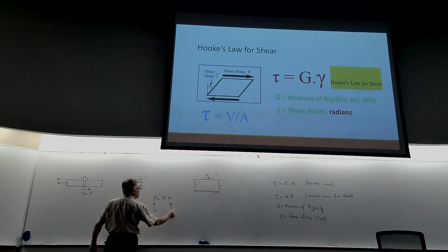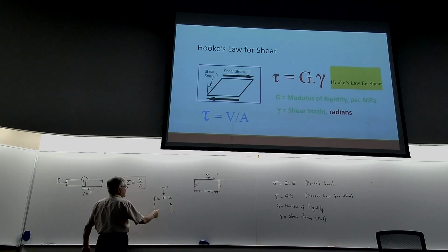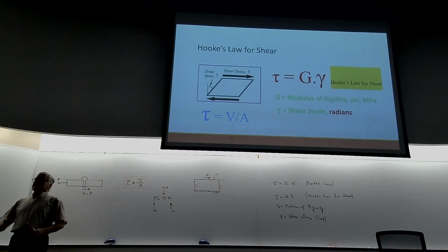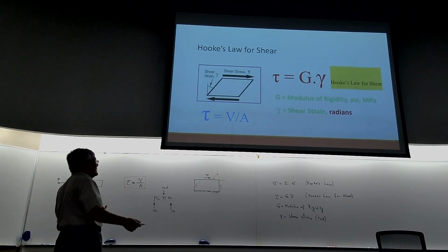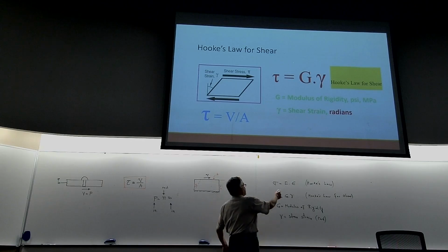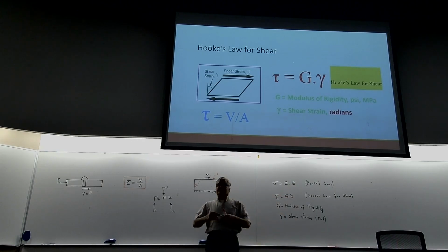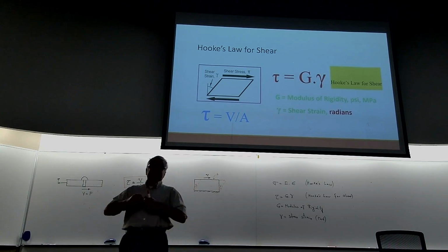Diameter also in inches, and pi is radians. So if you cancel the inches, you find that a radian is just there by itself. So it is not a real unit. It's a reminder that we are not doing degrees. So radians can always be thrown out as a unit, or they can be brought in as needed. So gamma is unitless, just like epsilon was. So it's never in degrees, always radians.